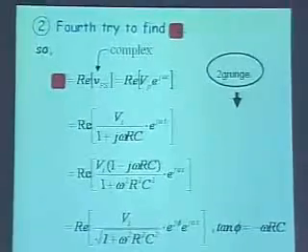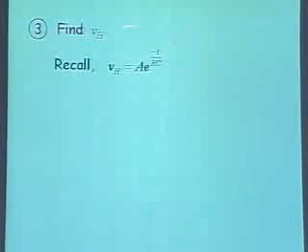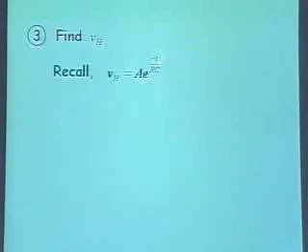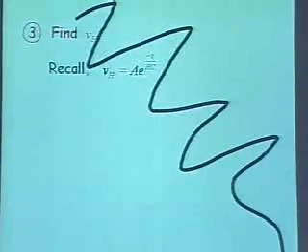I'm going to blast through two or three more view graphs that just give you more insight and more math, nothing particular. Remember, to solve the equation, we have to find a homogeneous solution too. But recall that the homogeneous solution for an RC circuit is of the form A e to the minus t by RC. This means that as time becomes very large, this part goes to 0. In the steady state, and remember I care about the steady state, this goes to 0. And so I don't care about the homogeneous solution.